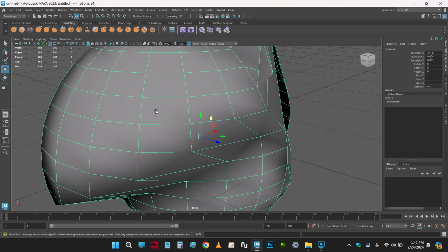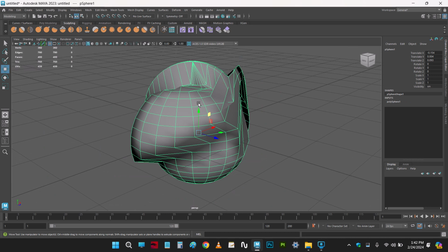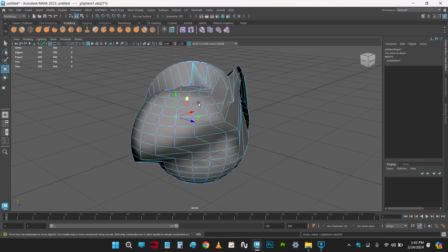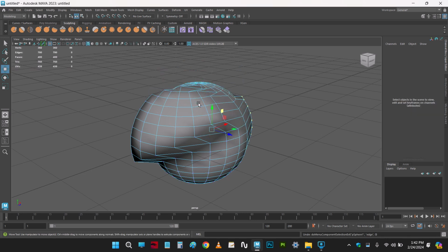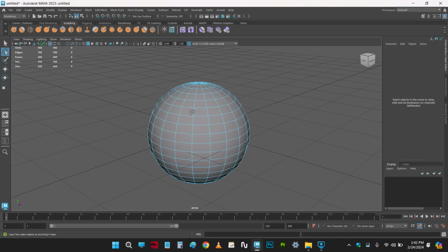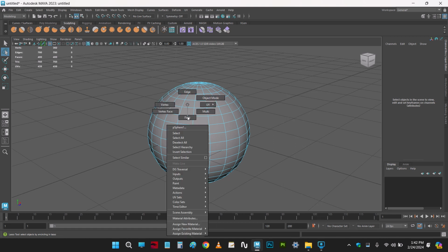Okay, so this is the thing. And then if you want to undo it, simply Control Z, we can undo. Now, coming to the lasso tool, this was done with the gizmo move tool. Coming to the lasso tool, it says okay, you are in the component. Which component? You need to select it. Nothing is getting selected. That means you need to right click on the object, or the other way, outside of the object, but the object should be selected.